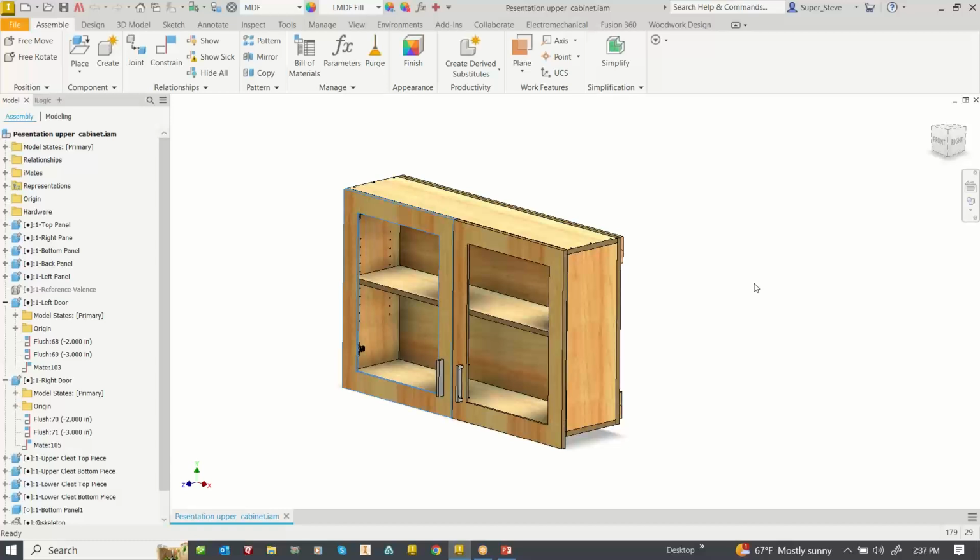The one thing one has to consider, though, is that engineering now controls the machinery. If I build something here and go directly out to machining, whatever I build should be machined exactly as I built it. Sounds logical to me. But again, that means tolerances. That means thicknesses and widths. That means materials. That means grain and grain direction. Because obviously the grain direction will make a big difference.